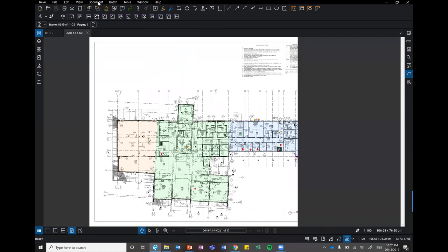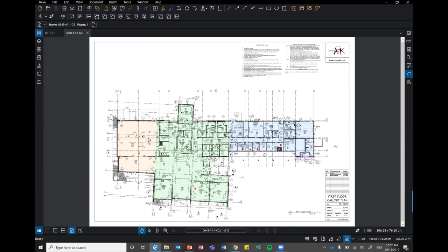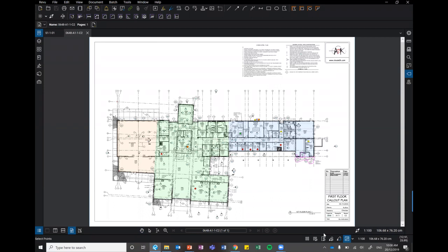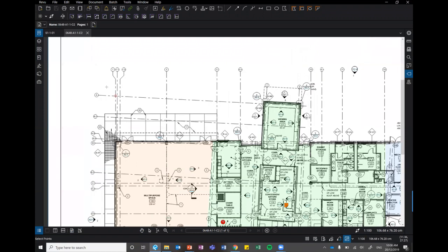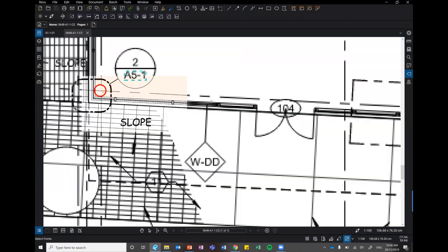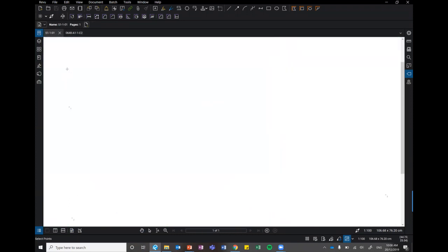So we have this opportunity in both overlay and compare, but I prefer overlay, to be honest, where we can actually use align points. So inside here, we can say, right, snapping on, snap to content. I've put some little cheats in here so I don't miss it in my demonstration, but I want to pick up 3 points that are common in both files. Boundary line works a treat because you've got nice corners. Grid lines, not always, because sometimes they don't intersect, which is a bit frustrating, but we should have a fairly good indication.